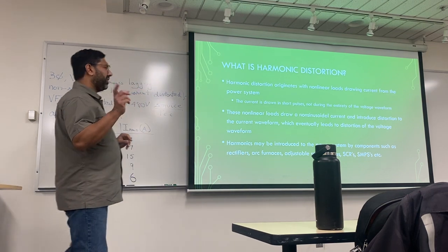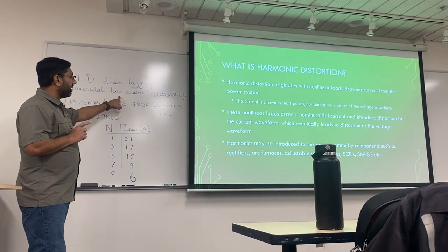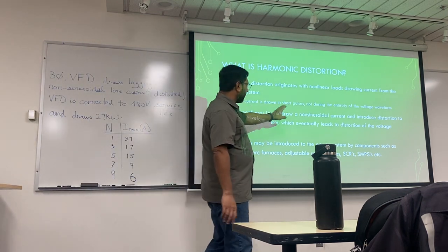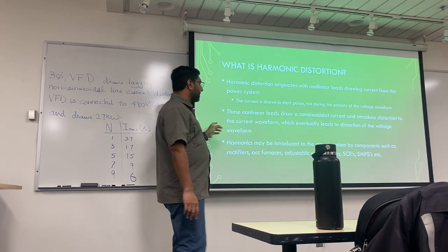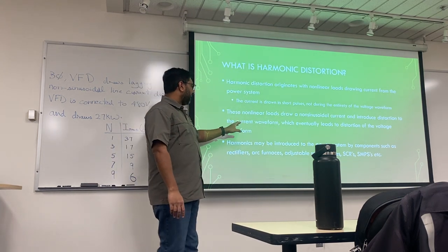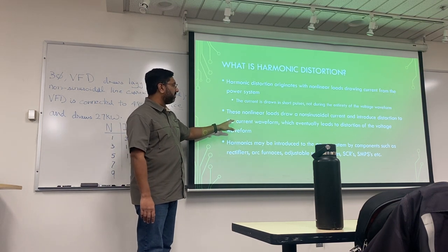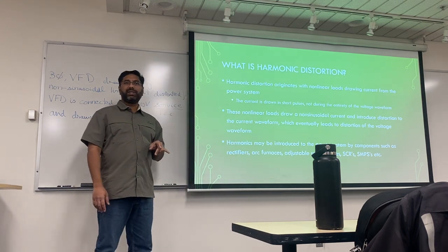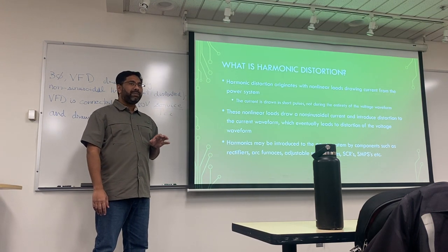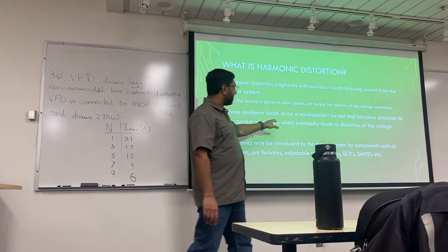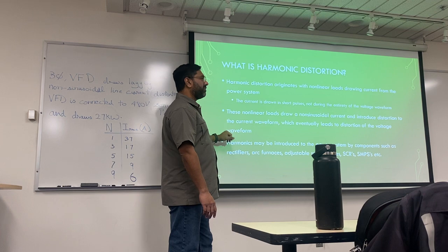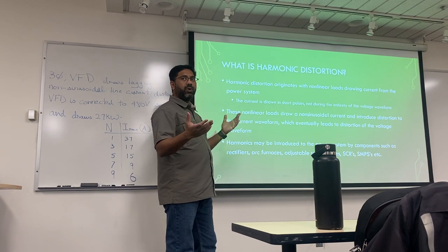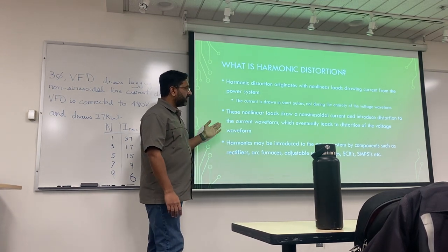I believe in your homework, there is a non-sinusoidal problem that you have. But for the time being, just understand the current would be non-sinusoidal, and that introduces a distortion to the current waveform. If the distortion is high enough, it will eventually create havoc in the voltage also. For the purpose of this class, 95% of the time, we are just going to deal with current distortion. We will talk briefly about the voltage distortion, but we will assume it to be 0. But don't be alarmed if you see voltage distortion as well.